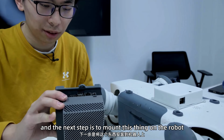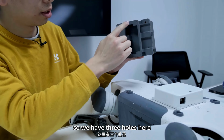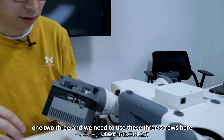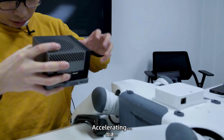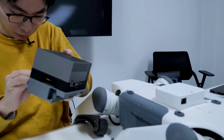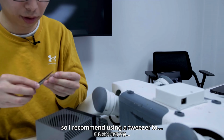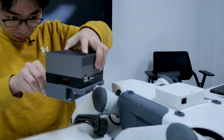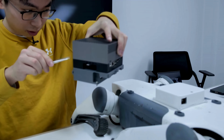And the next step is to mount this thing on the robot. So we have 3 holes here, 1, 2, 3, and we need to use these 3 screws here. And for these screws, it's kind of hard to install, so I recommend using a tweezer to hold them.